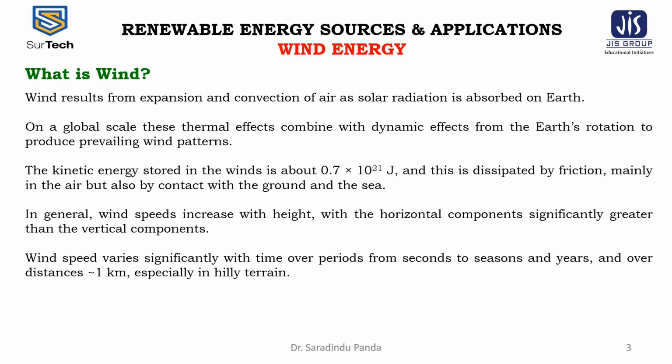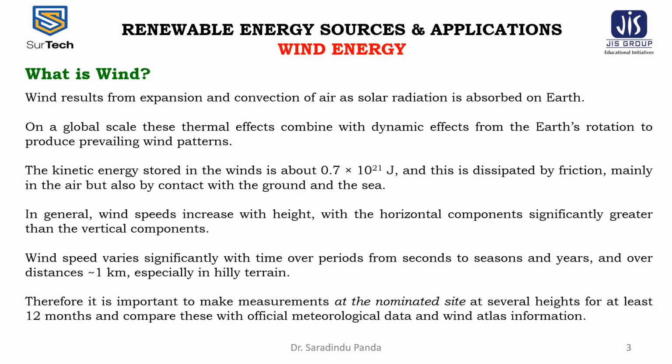Wind speed varies significantly with time over periods from seconds to seasons and years, and over distances of approximately 1 kilometer, especially in hilly terrain. Therefore, it is important to make measurements at the nominated site at several heights for at least 12 months and compare these with the official meteorological data and the wind atlas information.